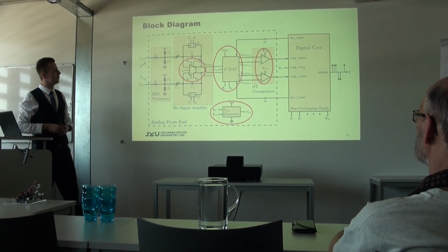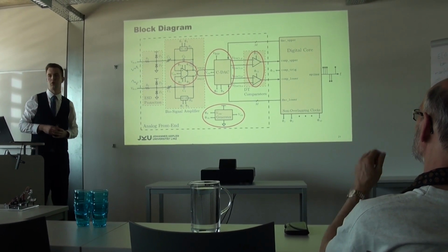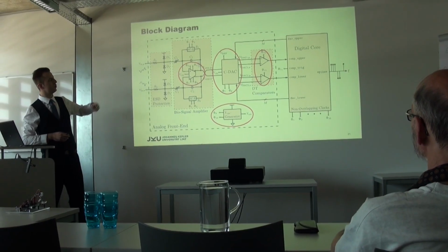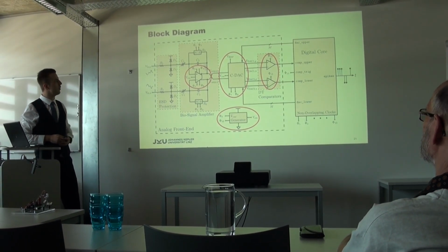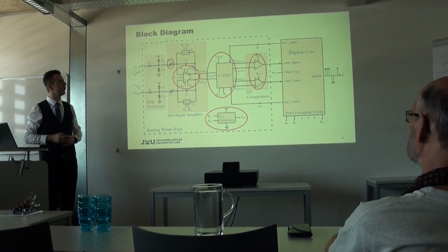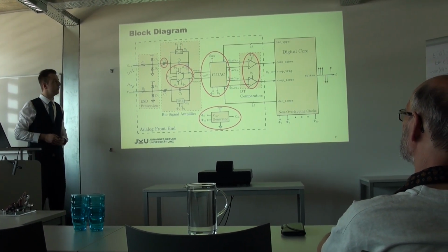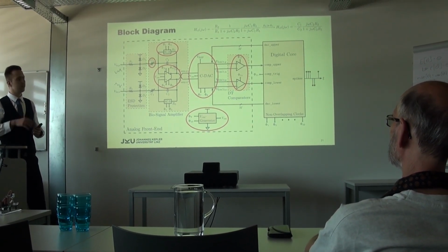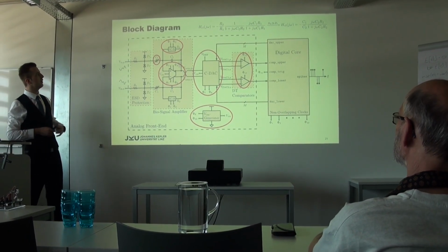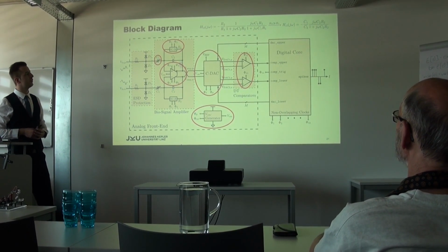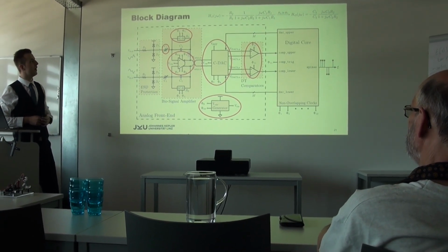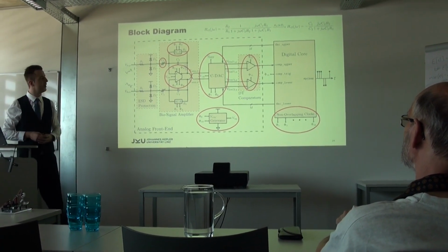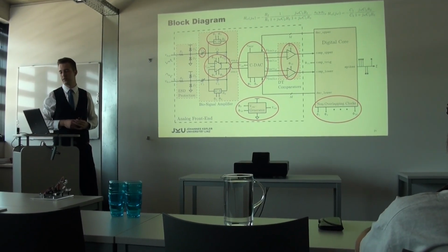The amplifier core consists of a telescopic input stage and a push-pull output stage, which are both biased by a beta multiplier reference. The common mode output voltage is set by switch capacitor common mode feedbacks. C1 is programmable, and we can adjust the gain of the amplifier. The lower cutoff frequency is programmable and can be set, for example, to 0.3 Hz, and is a 5-stage shunt capacitor, switch capacitor resistor, and all those switch capacitor resistors need a non-overlapping clock, and this is generated in the digital core and is synthesized.